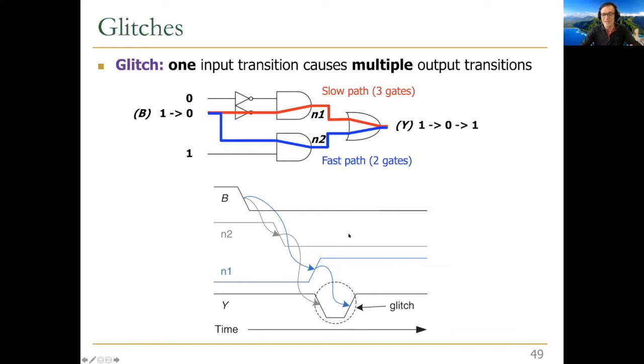So if you actually designed your circuit such that you sample the data at the time it is glitching, bad idea, right? Then you actually have a problem. Actually, it's a problem because you really didn't calculate the maximum propagation delay in your circuit very well. You didn't take into account the slow path, right? So you need to take into account your slow path. So if you take into account your worst case conditions and slow paths, these glitches should normally not matter. But again, that's a general rule that doesn't always apply. It really depends on what the designer does with the output signal.